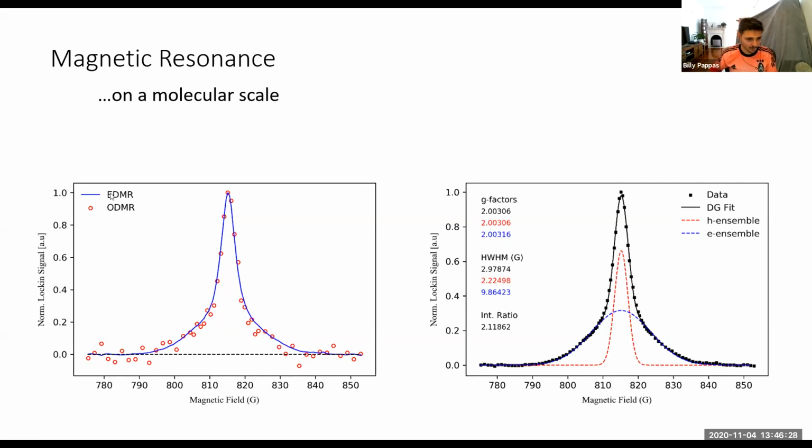Anyhow, we've done both electrical and optical detection to show that these processes arise from the same origin, and we can decompose this. If we take one of these signals, the EDMR, we can decompose it into two normal distributions. The line fit itself is a double Gaussian, and each constituent Gaussian arises from targeting the hole or the electron within all spin pairs in the organic material.